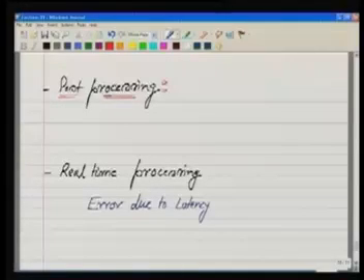One is post-processing. Post-processing means whatever the corrections are, these corrections are being determined after the survey. So the receiver is collecting all the data, meaning it is collecting the measured times, and the rover is also collecting the data, the measured time. There in the field, there is no communication between the reference receiver and the rover receiver. But once we come back to the laboratory, in the laboratory we find the corrections. So corrections are being computed in the laboratory.